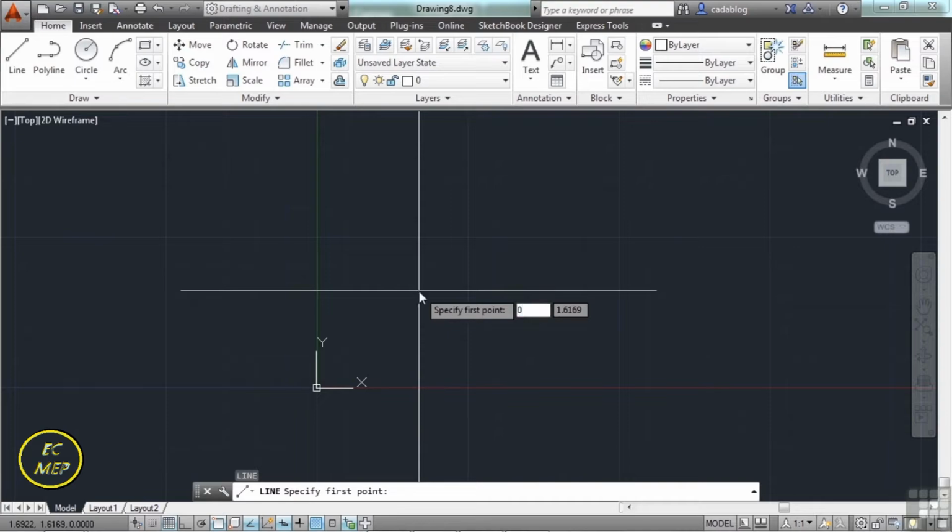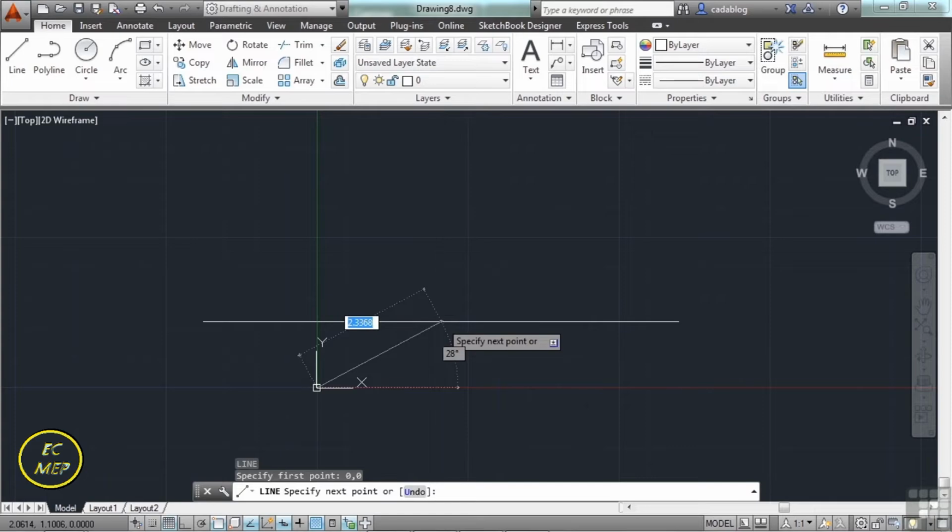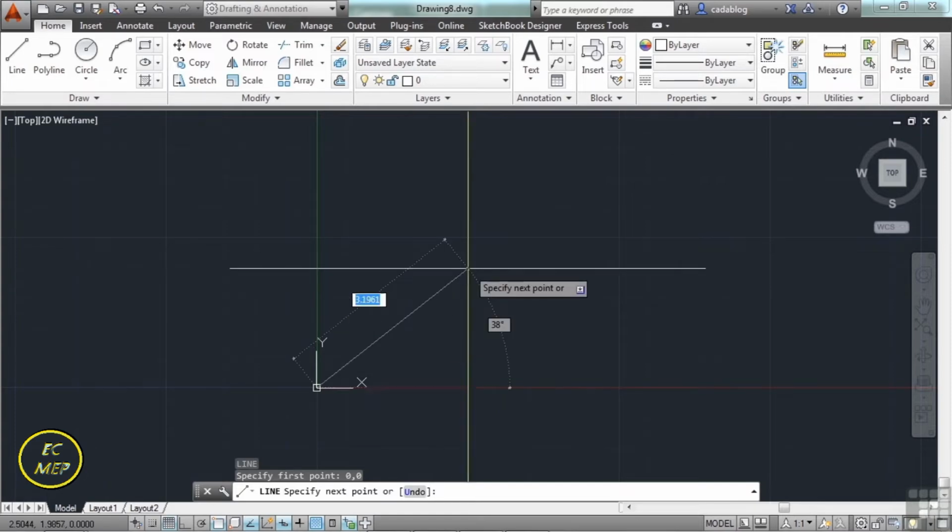And whenever you start off something, you can always just type in the coordinates. So put in 0 and hit the tab key or hit the comma key, either one in this case. And we want 0. Press enter. And my line is now started at the origin, or at 0, 0. Now it's a little tricky. On your next point, your second point, you have to tell AutoCAD that you want to put in the exact coordinates. Otherwise, it's going to put in distances and angles. So you have to hit the pound key. That will tell AutoCAD that you mean a coordinate. So we want to put this at coordinate 3, 4. So hit 3, and you can't hit tab here.